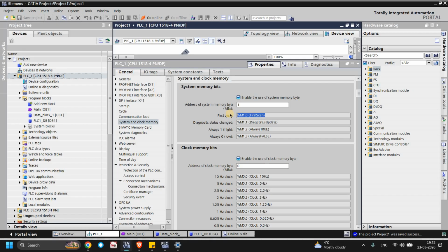after boot up, some logic will execute that you want to execute. That's what we call first scan. The first scan means the first time after power up that the scan will work. It's only scanned the first time. If you powered on, then it will not do it again. So it happens only once after boot up.